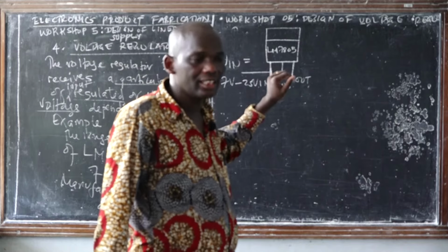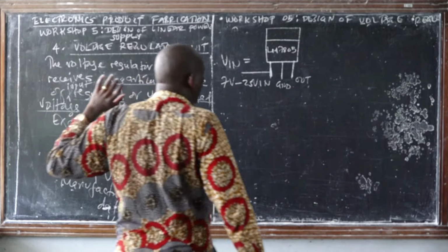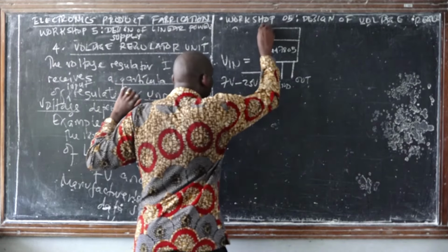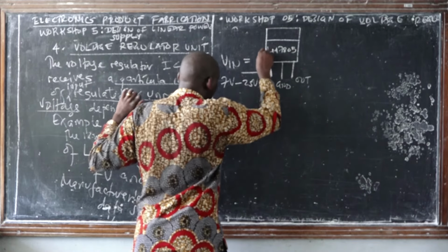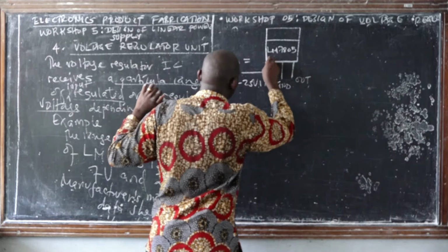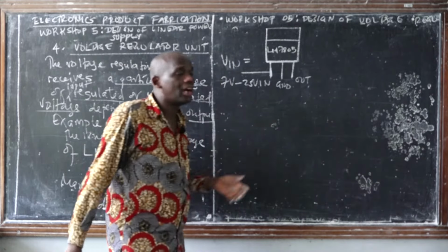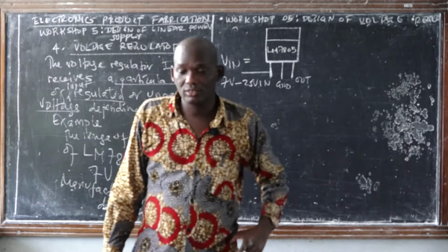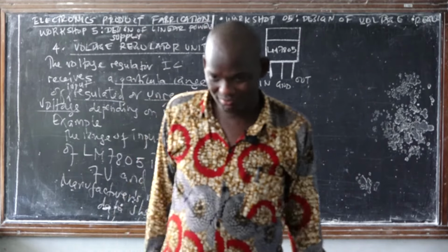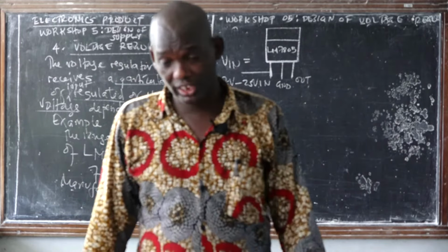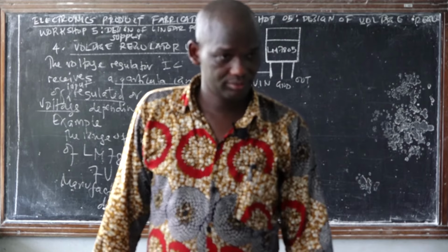But practically, you might find that you have designed your linear power supply. Today it's providing 5 volt, then you turn off your circuit and leave. The next day when you come back and turn on, you measure the output voltage and it is not 5. Maybe it's 3.5. Don't expect the other parts that need 5 volt to work.